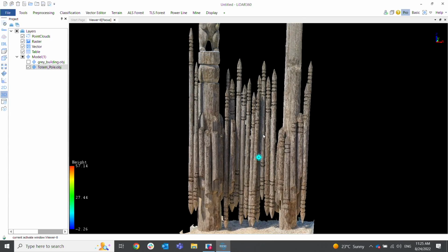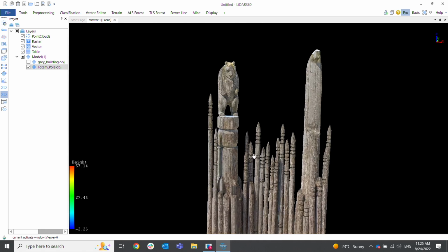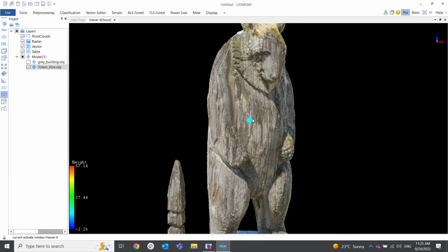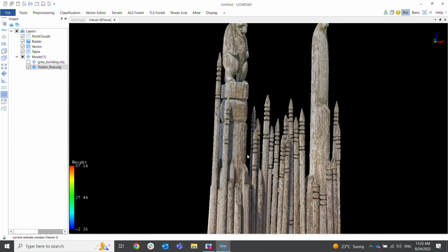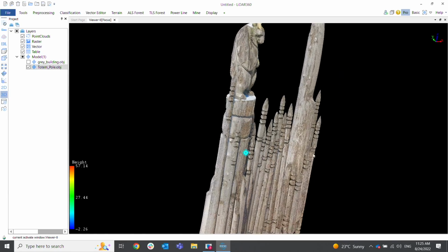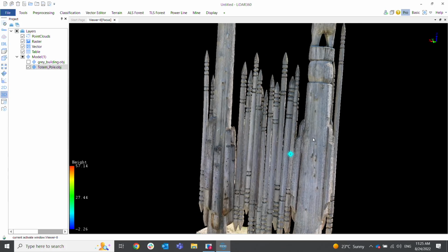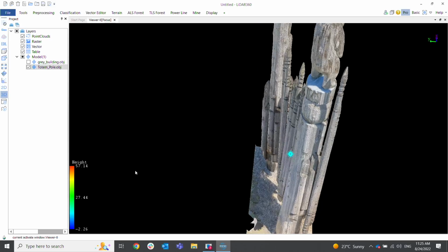Can we take a look at the model that we captured out on that day with the totems? Yeah, here we go. So we have the mesh, the mesh with the texture layer on, for the totem poles that we captured. You can see that if I zoom in on the bear, we get some really great texture, right? Now, obviously, because we did it in a very challenging environment, on the front we can see it's slightly brighter. We can see some shadows baked into the texture model. On the back, we were able to fix the model by enhancing some of the contrast, the highlights, and the shadows, and be able to stitch it all together.